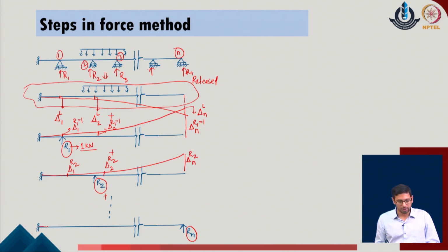And similarly, we can keep on doing this for all the n values of the loads in the given system, and that will give us the respective deformation profile of the given system. Now, as we want to define the compatibility conditions, we typically define the compatibility in the direction of the selected redundants. So, we have R1, R2 and up to Rn selected redundants of the given problem.